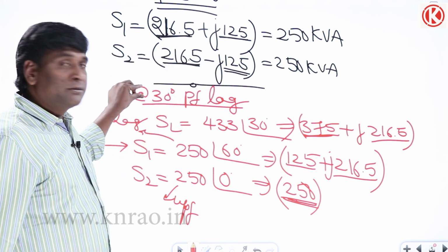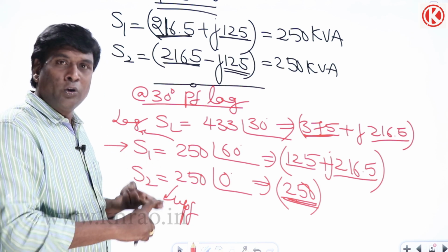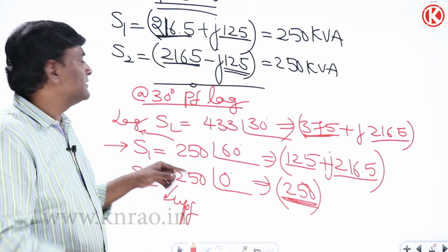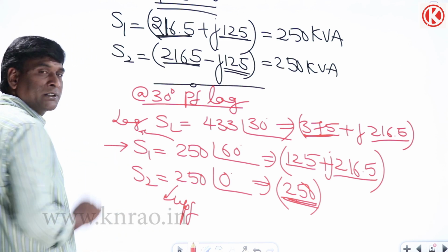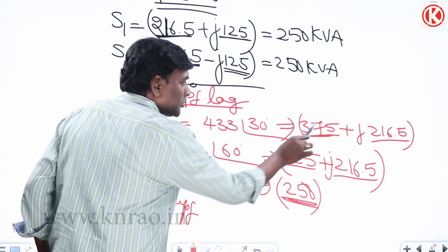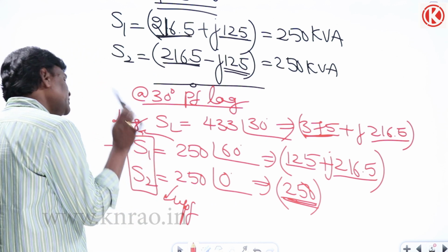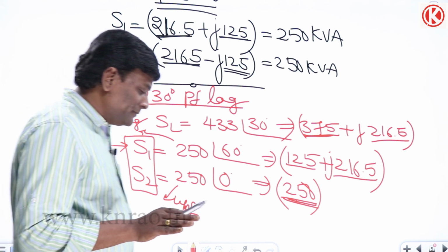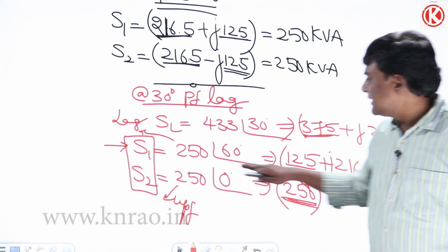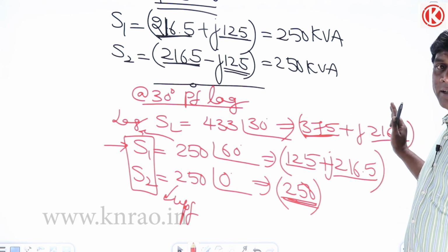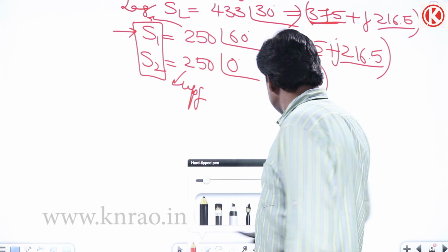So this load has a phase difference of 30 degrees between load voltage and load current per phase. Then inside the transformer, my conclusion is that between these two transformers there will be no reactive power supply and reactive power absorption. Whatever the reactive power supplied here goes directly to the load. Okay, let me think of 60 degrees.